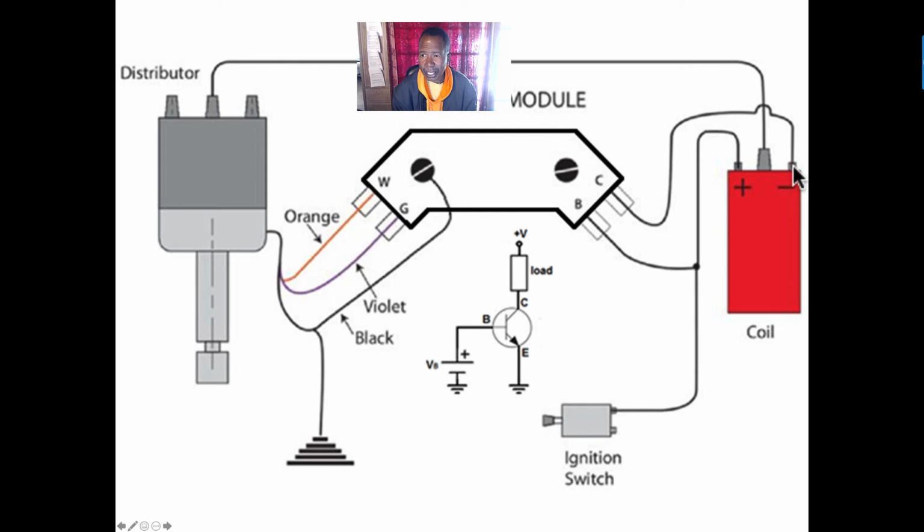When I lose my voltage at the base, I lose my ground here. And I get spark out to the distributor that feeds the spark plugs, through the cap, rotor, spark plug wires to the plugs. So, with that said, if I take a test light and ground it and put it here, I should see that test light blink, indicating that my transistor is working.